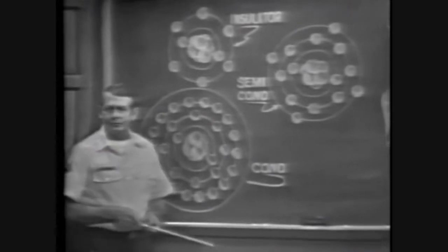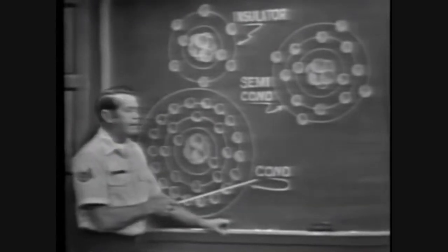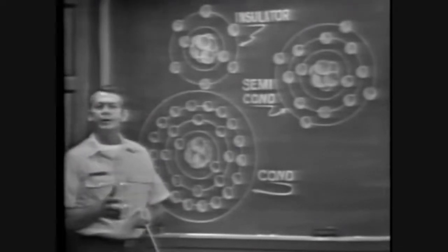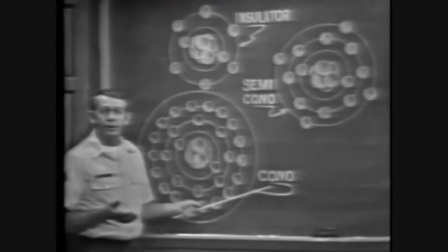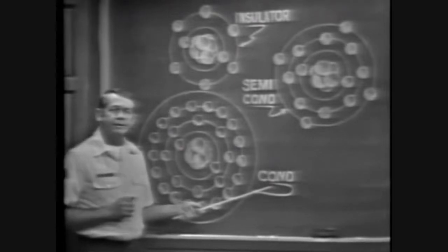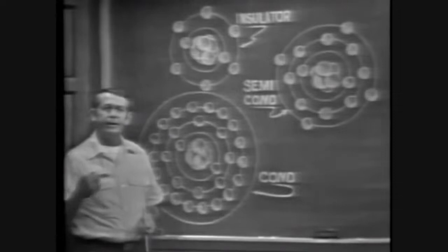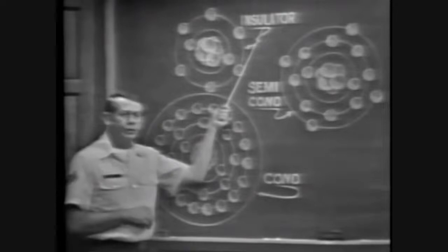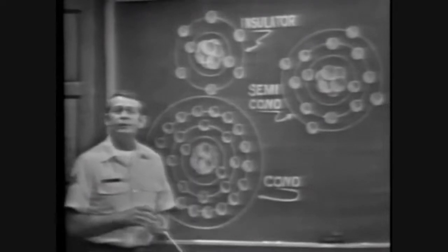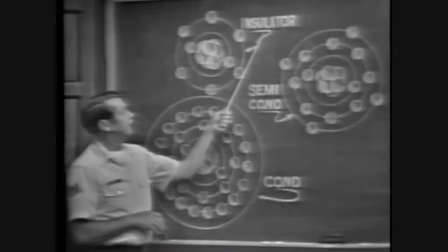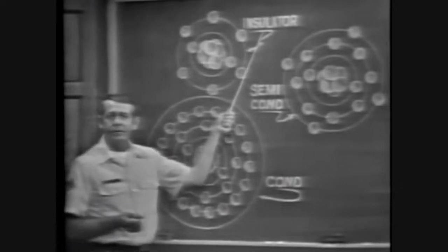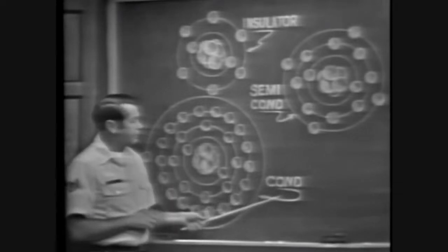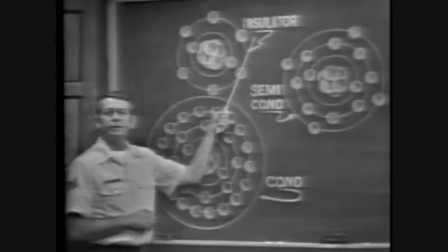Basically, it's the atomic structure of the material. For example, we've said that conductors have many free electrons. They allow current to flow with ease. If conductors don't oppose current, then they must have very little resistance. Well, that's why the wire burned up earlier. It was a copper conductor. On the other hand, insulators have very few free electrons. In most cases, they prevent current flow. Insulators then have a high resistance. That's why a large voltage was required to move electrons through air. A low resistance here, a high resistance here.